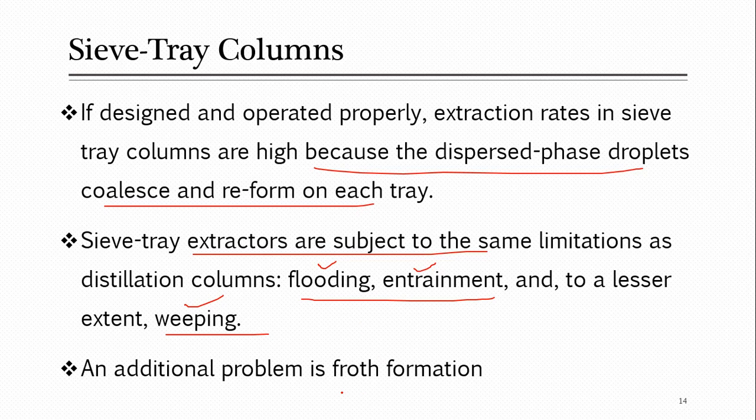Yes, an additional problem is froth formation. Froth formation also takes place, as we have discussed in absorption as well as distillation, and the same problem takes place here. And what is the issue with froth? Just think over it. When froth takes place, the contact between the two phases reduces, like the contact of liquid and vapor is reduced. On a small scale, if you remember from absorption, there was froth formation, but if it is extensive, too much froth, then there will be a problem.